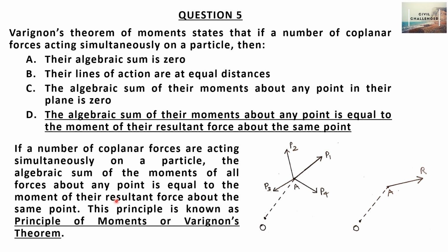Okay, this is known as the principle of moments or Varignon's theorem. Therefore, the correct answer is option D. Varignon's theorem of moments states that if a number of coplanar forces act simultaneously on a particle, then the algebraic sum of their moments about any point is equal to the moment of their resultant force about the same point.